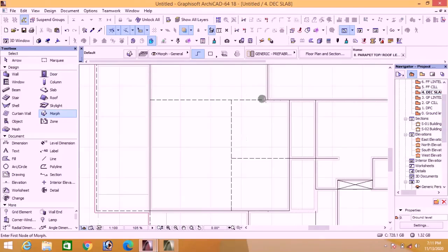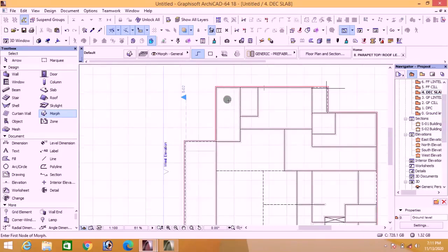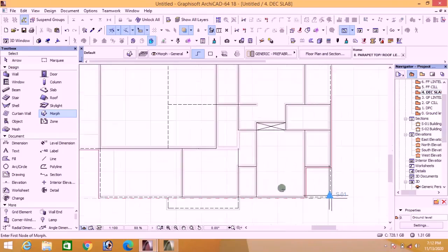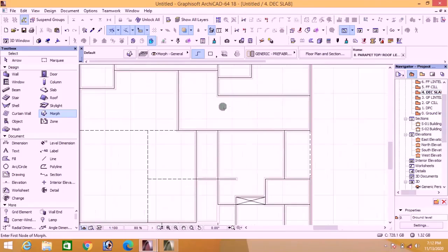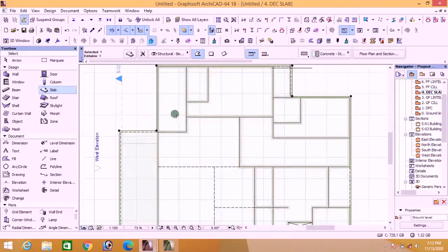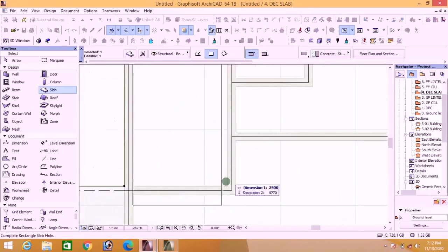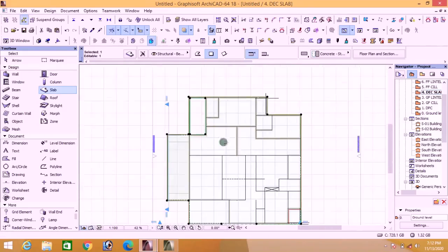this place. Cut this place open. We also cut this place open because what we have here is the stairwell. This is your staircase, so you have to cut this place open for the construction of our staircase. So click on slab and then highlight this slab and change it to rectangular selection and pick it to this spot. It's now open for your stair.